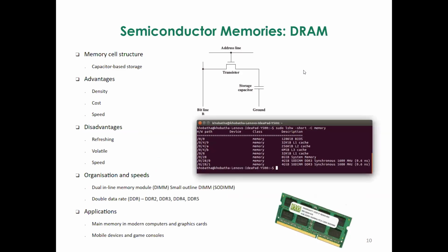So this is DRAM. We have already introduced it, that this is dynamic and random access memory built using a capacitor, meaning the single memory cell, which is used to store 1 bit of data, achieves that through a capacitor. So when the capacitor is charged fully, then you have a 1 written to that cell. When it is discharged, then you have a 0 stored in the cell.